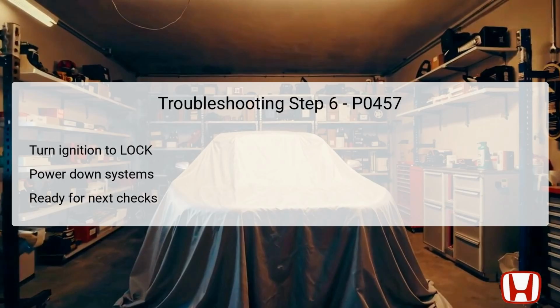At this step, turn the ignition switch to the lock position, designated as position 0. This action helps to ensure that all electronic systems are powered down, thus preventing any unintended operations during the upcoming checks. This is a critical safety measure before any hands-on work is performed on vehicle components, especially those related to the EVAP system. Ensuring that the systems are completely shut off allows the technician to safely remove various components, such as the EVAP canister vent shut valve, in subsequent steps.